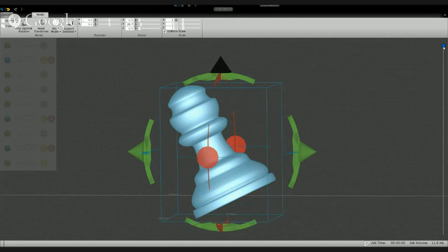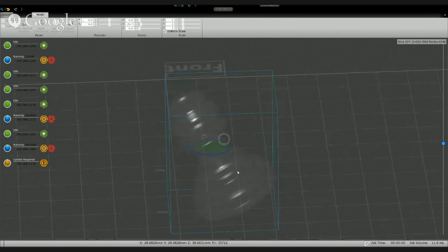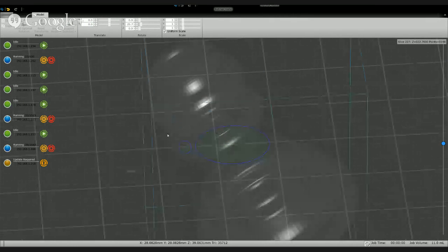So if you go through the slicing, there's a part right here. Let's see. There's a part right here where, when the model is printing upside down, this will appear floating, separate from the model. It's only floating for one slice, but then it's barely attached for another slice, and then it's pretty securely attached. So it probably wouldn't fail, but there's a chance it would fail to print because it's unattached and it would sort of have a cascading failure.